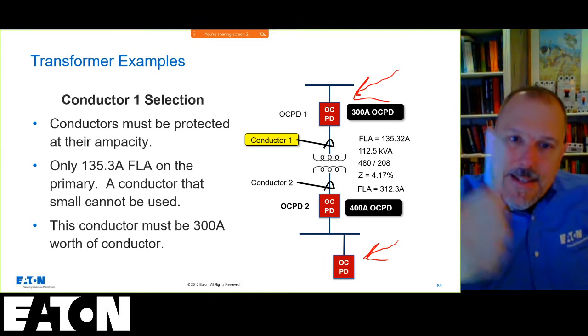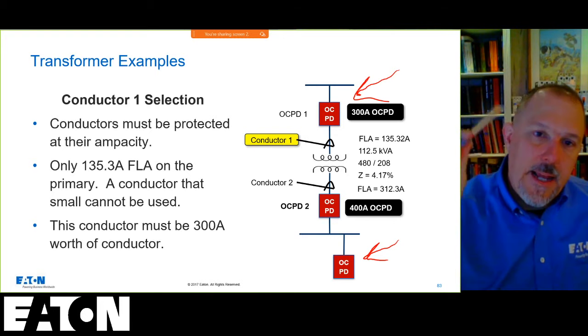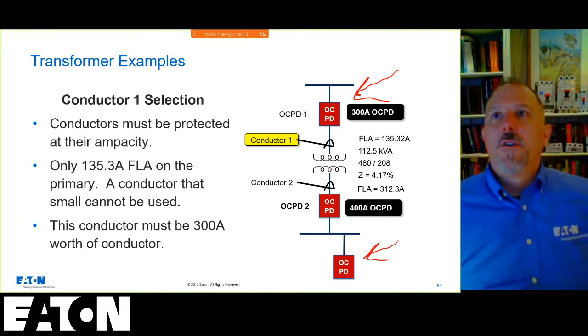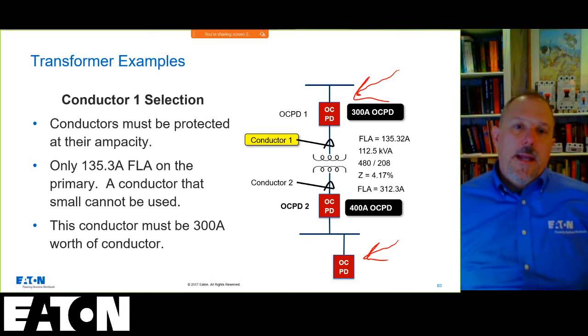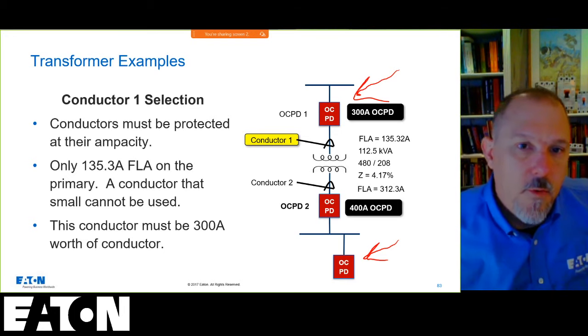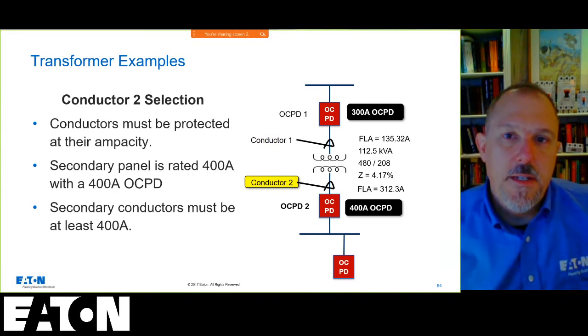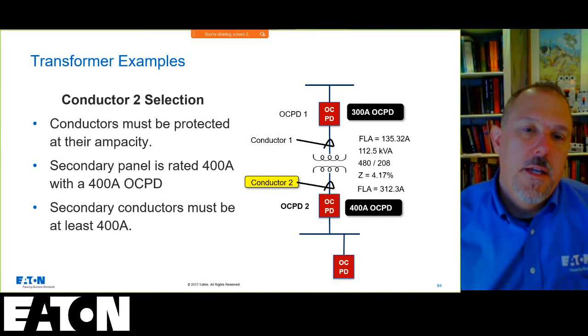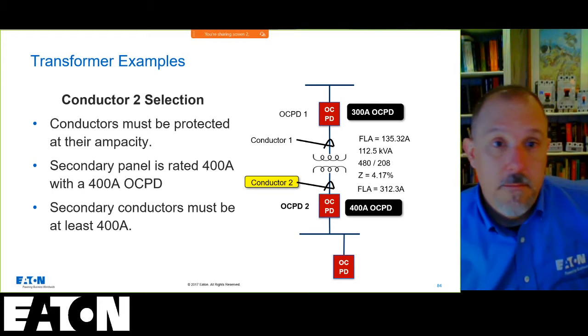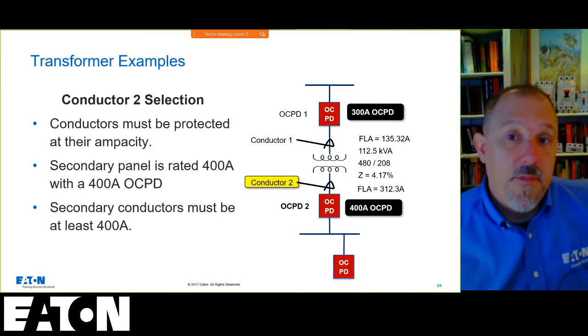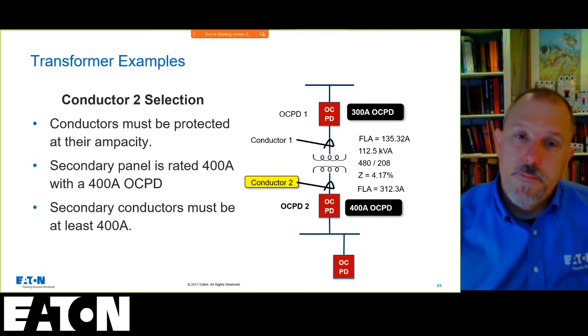And to get that done, I might need a larger primary overcurrent device. So it's good to know what your maximum is. What do we typically do? 125%. That'll save me some conductor size, ampacity size, smaller pipe. And if you have to bend it, it's easier to bend.